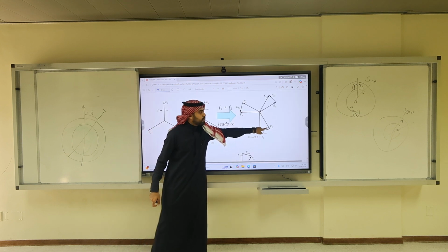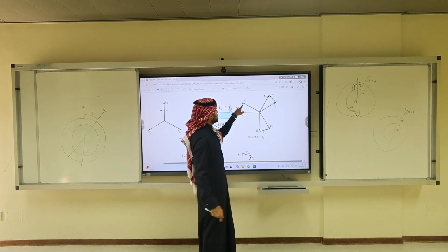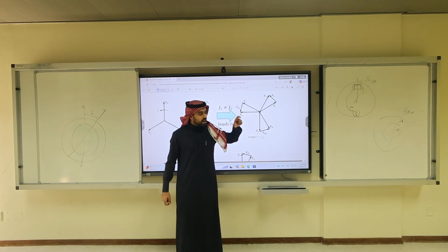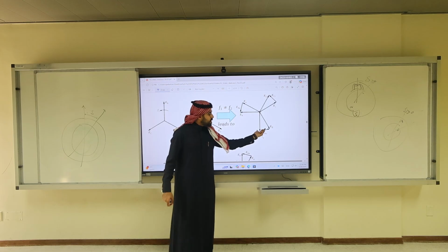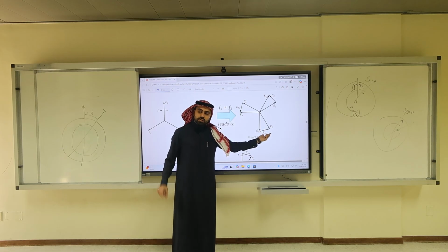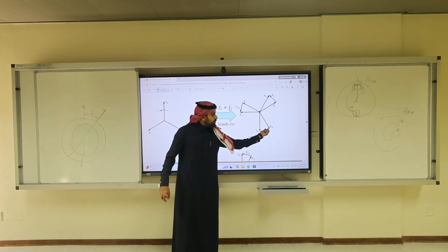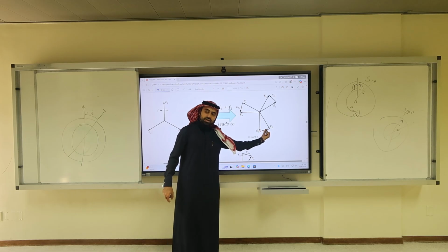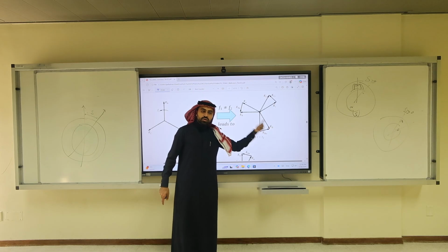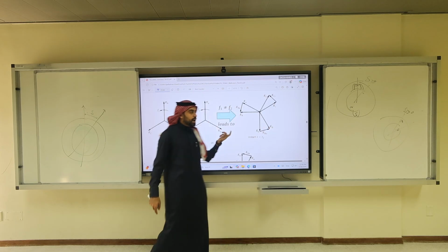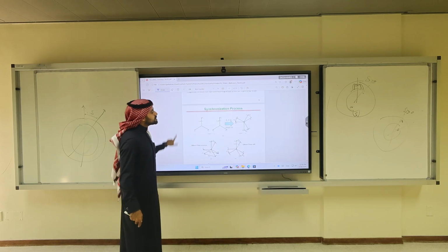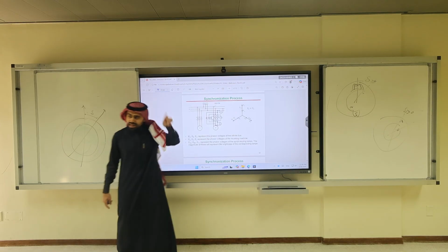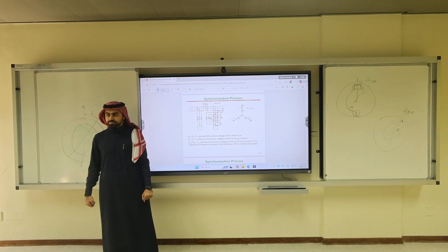These small arrows are ECC, EAA, EBB. If we have synchronized, these are the voltage across the light bulbs. If they are there, then the light bulbs will be flickering. If they are synchronized, if the frequency is the same, this arrow will be 0. So they need to have the same frequency. What this implies is that both rotors of A and B should rotate at the same RPM.